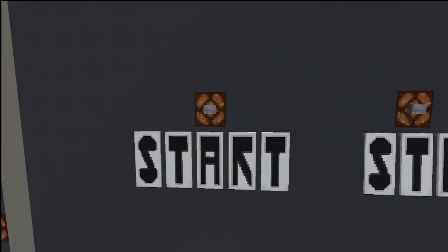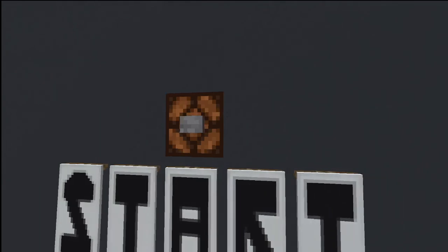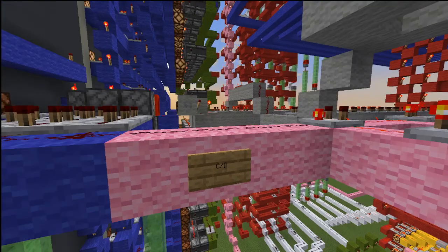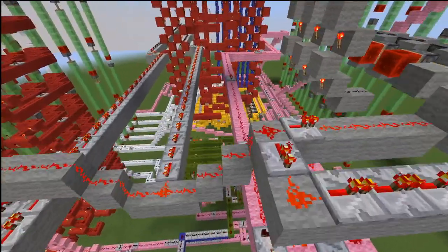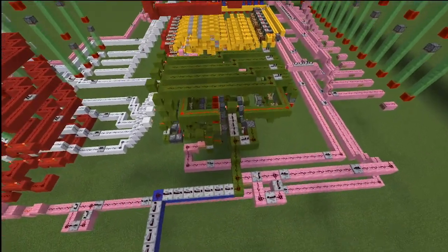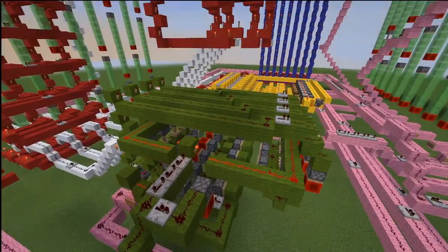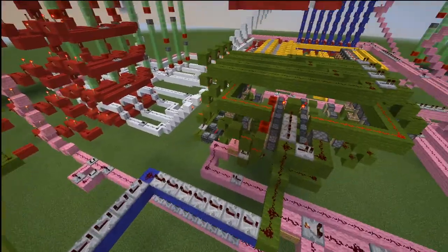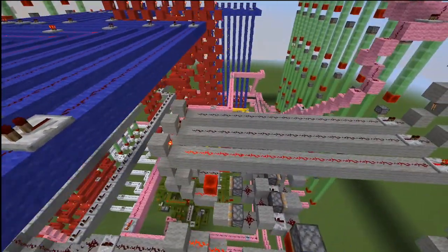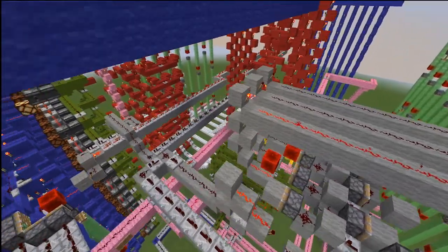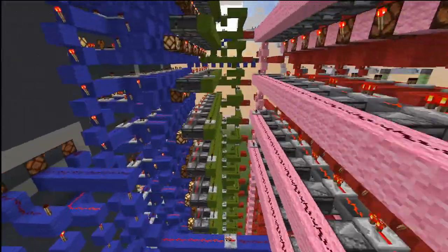So let me switch so that I can interact with this button. And I'll switch back, and you can see what's happening. It's going to be laggy because I'm recording, and the recording software lags up my computer quite a bit. So this is going to reset the program counter right here. This is the program counter. I believe it already reset, and the clock is running. So when this clock pulse comes back around here, it's going to update this. And now we should have our first micro instruction for the clear running.